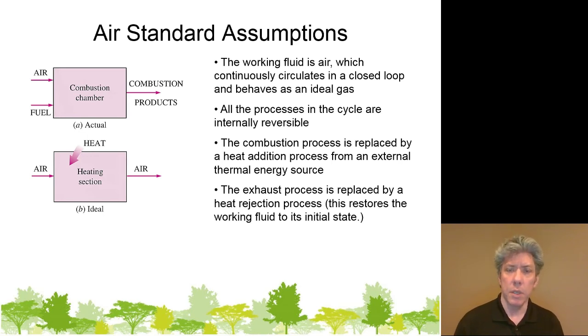The next assumption is that instead of putting air and fuel into the combustion chamber and literally burning the fuel, we're going to assume that there's no combustion at all, and the heat is simply transferred to the air, thus increasing its thermal energy, just like the purpose of the fuel. And so instead of having a combustion process, we'll have a heat addition process.